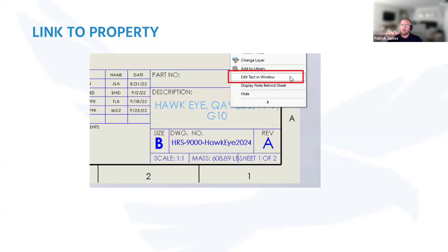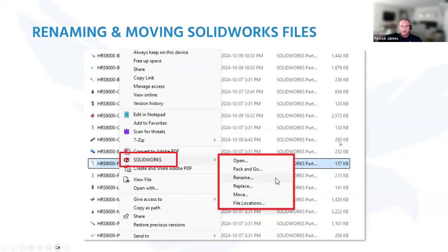Pro tip for really anything SOLIDWORKS: if there is a way to click through or go from a drop down to put some sort of property or operator on, do it that way so you spell it correctly every time. I know I've tried to type things in and it just shows the thing I typed instead of converting to the material I wanted or whatever it was. So yeah, if you miss a space or a quotation or something, it just uses static text. So pick your drop downs whenever you can here or in equations or wherever you're using SOLIDWORKS. If they've got a list for you to pick from, do that. It'll be the perfect syntax every time.